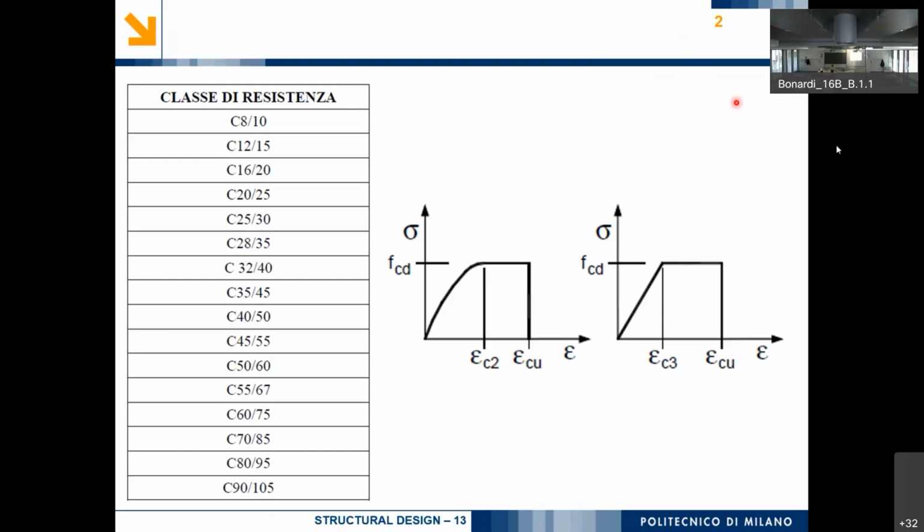Okay, right. Well, the third one, I will spoil the last one, is the constitutive law. All the materials, both the steel and the concrete, exhibit a linear behavior, so that the strain is proportional to the stress, and vice versa. Obviously, this holds for the steel both under compression and tension, but the concrete only reacts in compression. So the second hypothesis is that we assume the constitutive law of the materials is elastic linear.